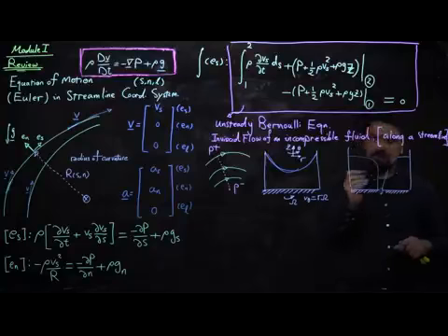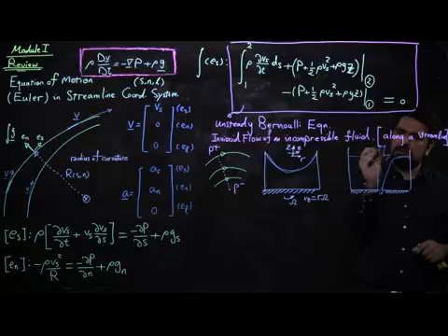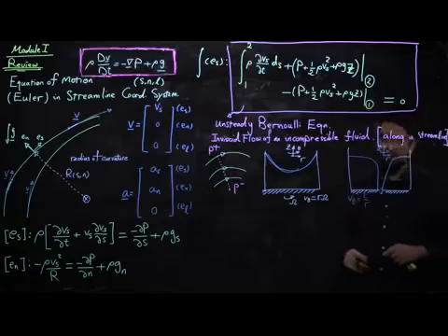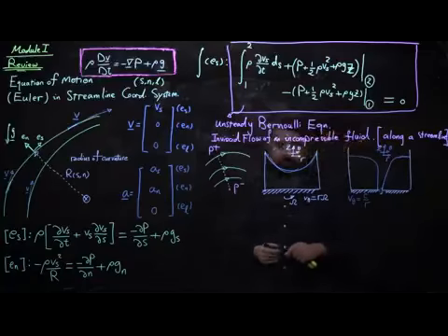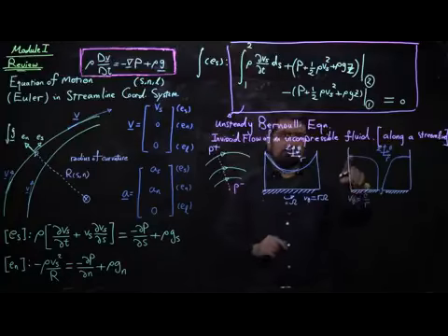And we notice that again, we used the concept of cylindrical coordinate system, r, z, theta. And here, V theta was constant divided by r to conserve angular momentum. And again, we saw that being further away, you get a larger pressure. That's why the profile rises to a higher value.